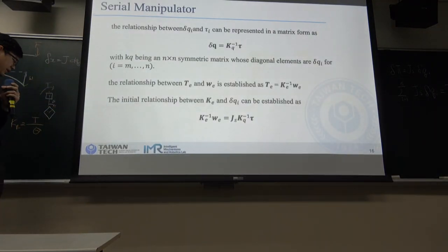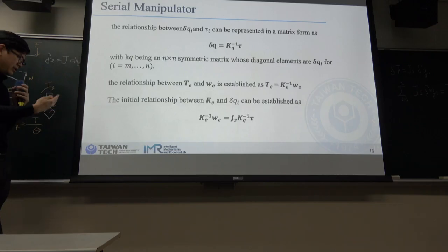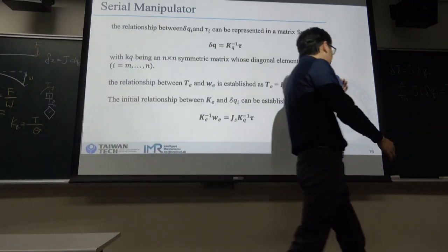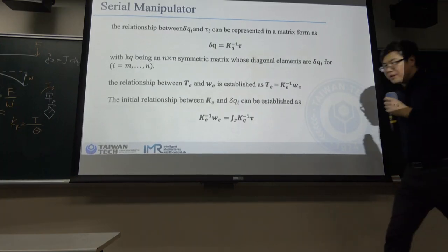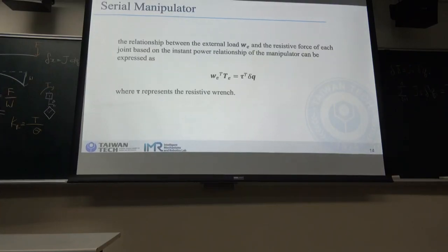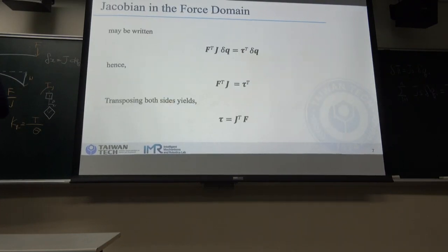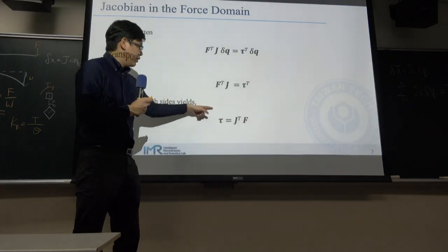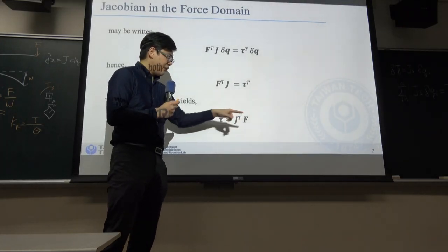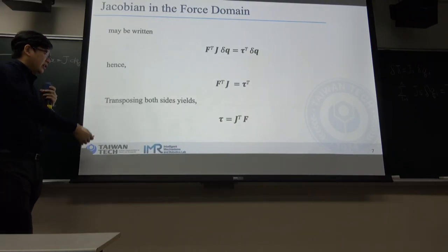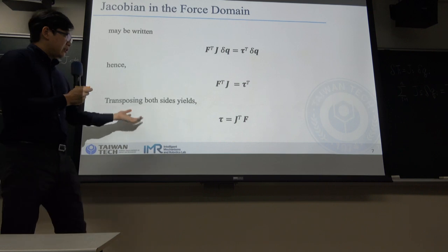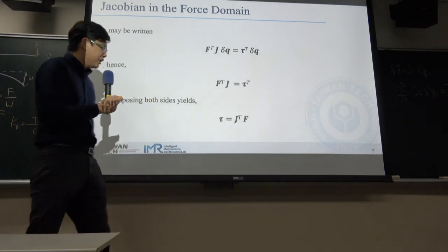I know maybe the calculation is more complicated. Is it okay for the calculation? Because all the thing we use is basically this formula: torque equals Jacobian transpose times force in our statics model. And the stiffness is one of the applications of using the static formula.